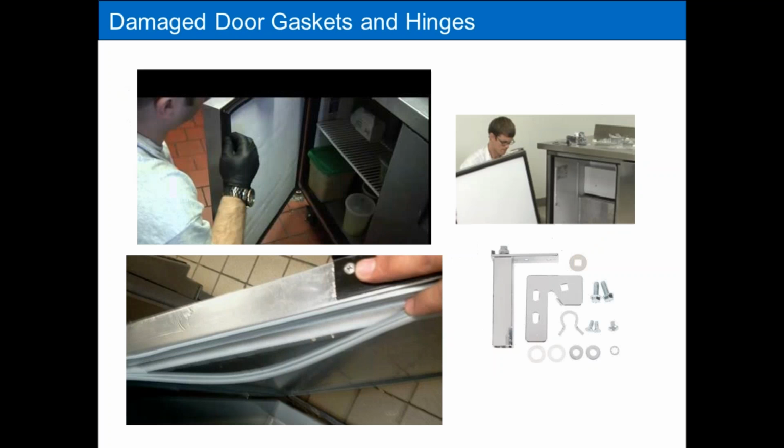Don't forget to look at your door gaskets, door hinges. If you don't have a tight compartment, you will not make temperature. That could cause a case to freeze up or not maintain temperature, so always inspect your door gaskets, make sure they're in good shape. A torn, ripped door gasket can cause you grief, and it's not a mechanical problem, it's a hardware problem. Same thing with a door hinge. A door hinge that's not making good contact can cause grief.